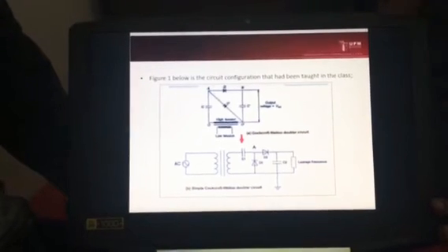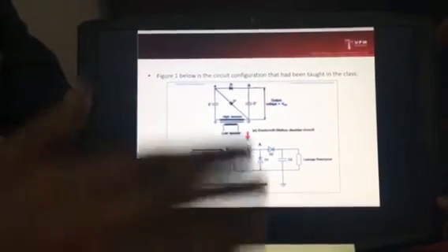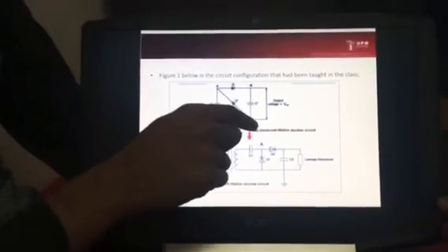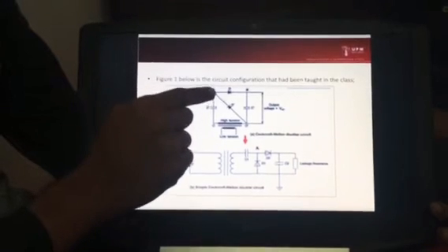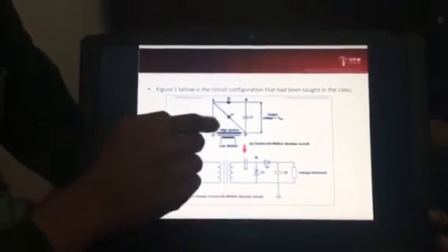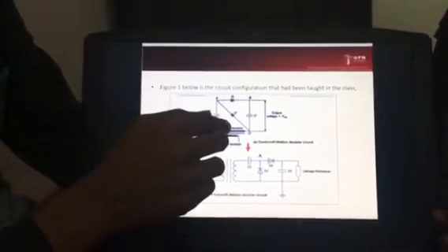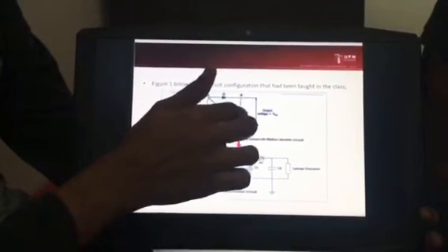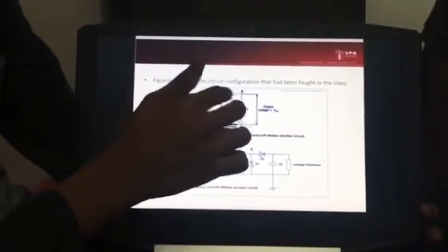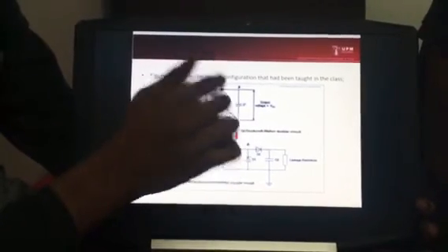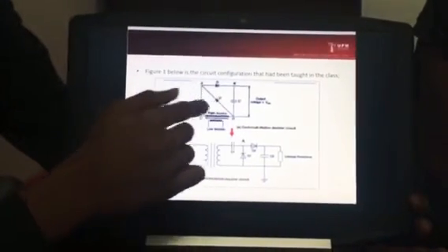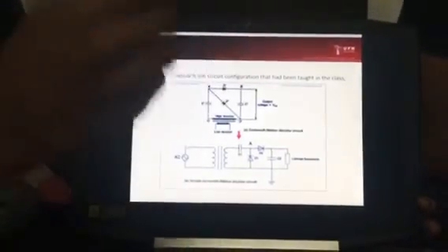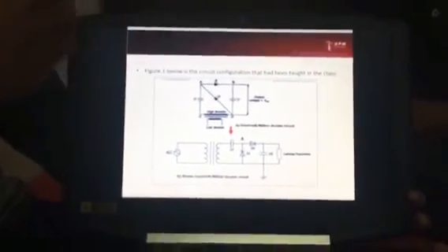This circuit is like a full wave rectifier, with a negative cycle and a positive cycle. For the positive cycle, the current goes from 0 through diode D1 to A and to the capacitor. The capacitor will charge, and when it is charged it reaches Vmax. Then for the negative cycle, it goes from A through the diode to C. After C1 is charged, it transfers to another capacitor, so it produces 2 Vmax because of the capacitors. This is Vmax and this is Vmax, and we call it 2 Vmax. That is why the output is bigger.